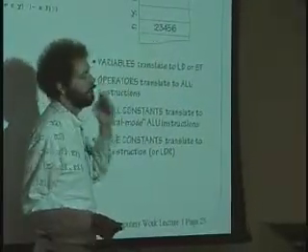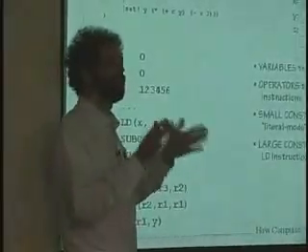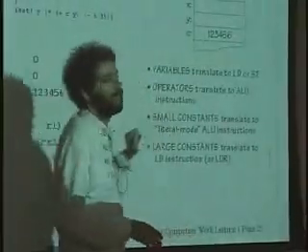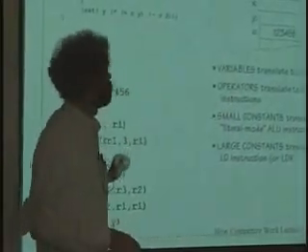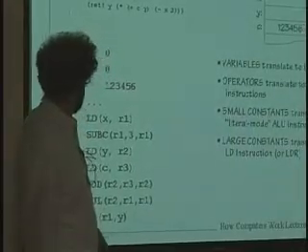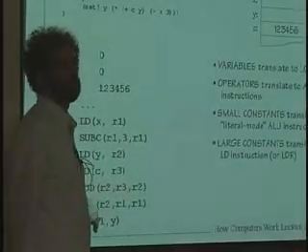So the way that we get around the limit of how long a constant can be is whenever we have a constant that's bigger than 16 bits, we give it a word in the data section of the big slow memory, and then we just get a pointer to it and we get it from there. Okay? So as an example, here we load C into R3, and that puts this big constant into R3, and then we can now use it in our code down here. Okay? Again, I'm going through this very, very fast, I know, and I know that most of you are not going to get most of it, but that's okay. Very, very quickly, because you're all going to get to do it, okay? And you'll learn it like that. But I want to show it to you first.